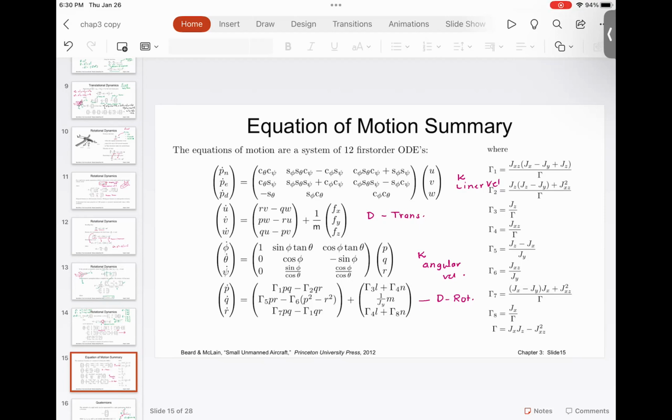These are the torque about X, torque about Y, torque about Z. So basically, on that aircraft, we have 3 external forces, Fx, Fy, Fz, and 3 external torques, L, M, N, about its body axes, body X, body Y, body Z. Everyone understood this? So what we are going to do is, in the simulation, we are going to input those forces and torques and see how the aircraft flies.